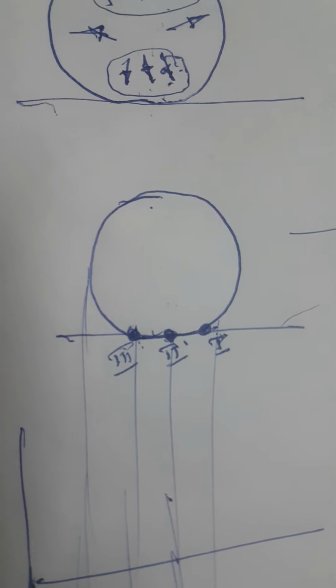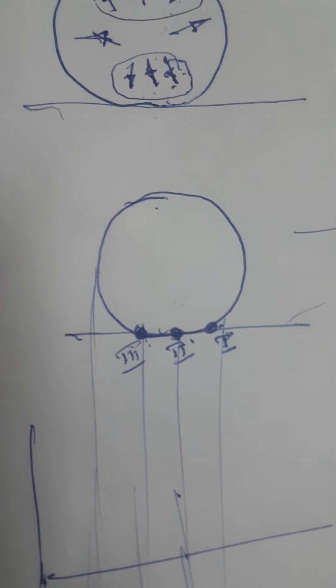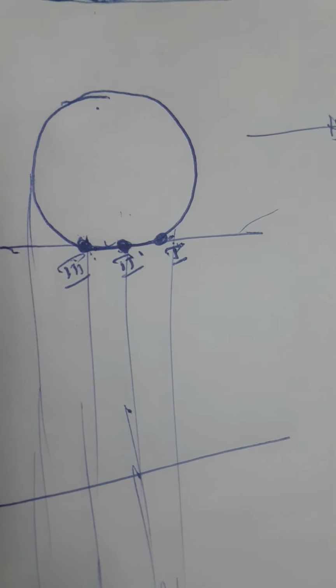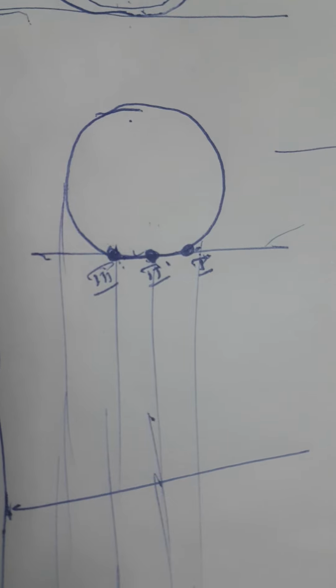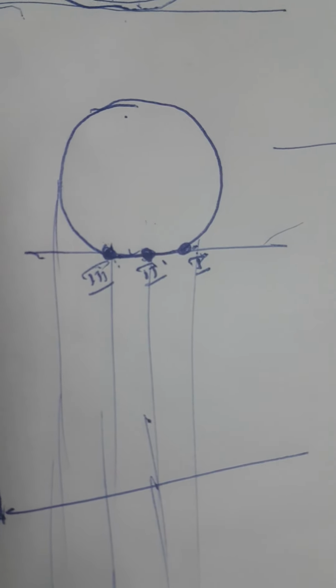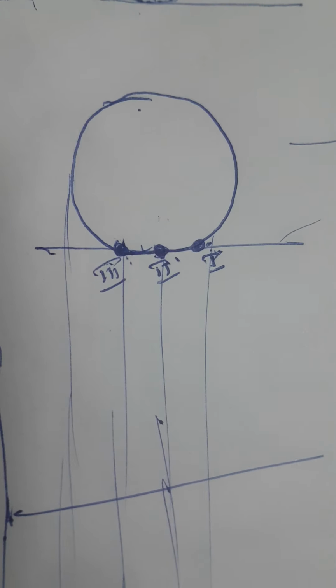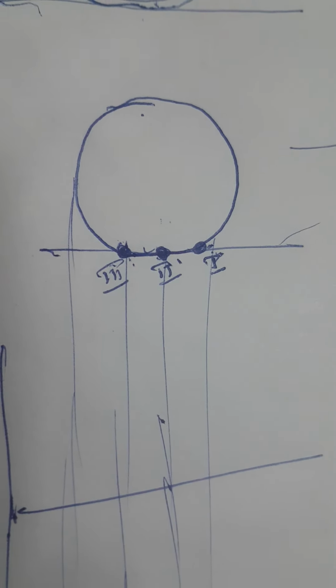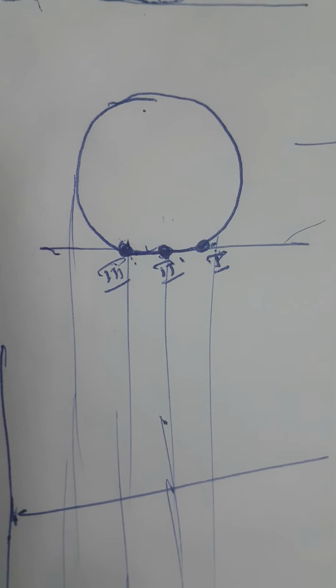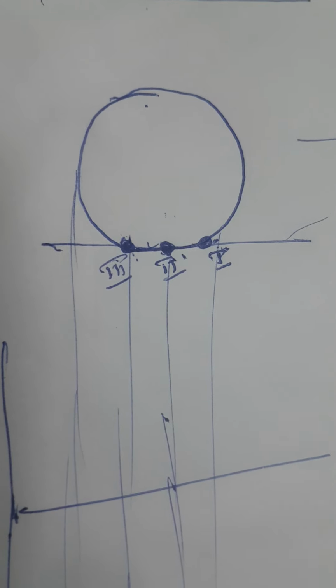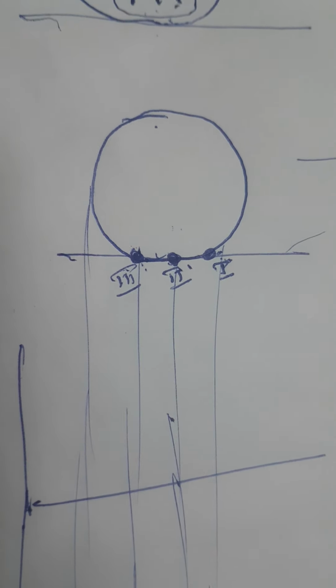Okay. As we discussed in our classroom, we have seen the tire and road surfaces in microscopic and macroscopic scale, and the pressure developed inside the tire is not going to be symmetric, because it has to maintain the equilibrium condition with tractive force in the longitudinal direction and vehicle weight, I mean vertical load, in the vertical direction.